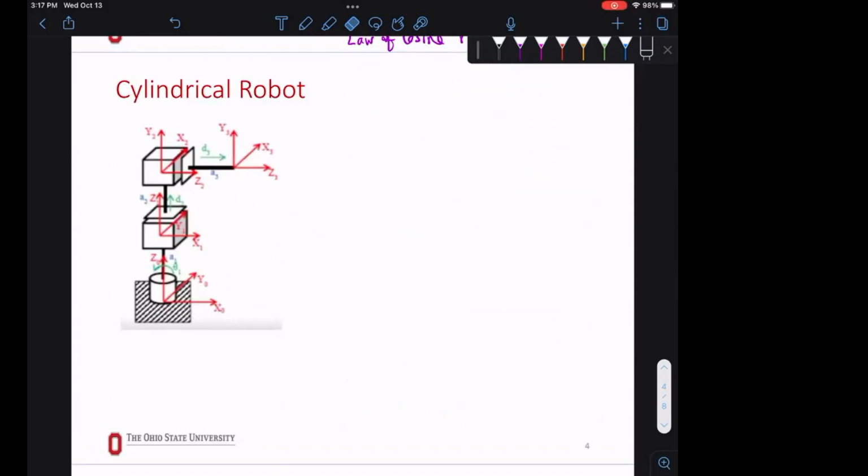We are going to find the inverse kinematic expression for this robot. Once we have the expression for any given coordinate of our end effector, we can find our joint variables, right? Now, first of all, what is the joint variable? Adnan, what are our joint variables? Theta 1, D2, D3. This means that I have to write expressions to find theta 1, D2, and D3.